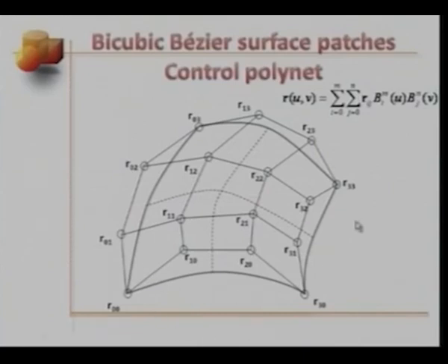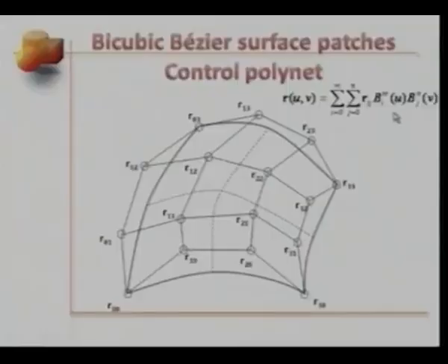As you know, Bernstein polynomials are barycentric, but that's not a local property, as we had seen in case of B-spline basis functions. Rather, if we use B-spline basis functions over here in place of Bernstein polynomials, and we'll be studying these models later, the corresponding shape changes will be local.